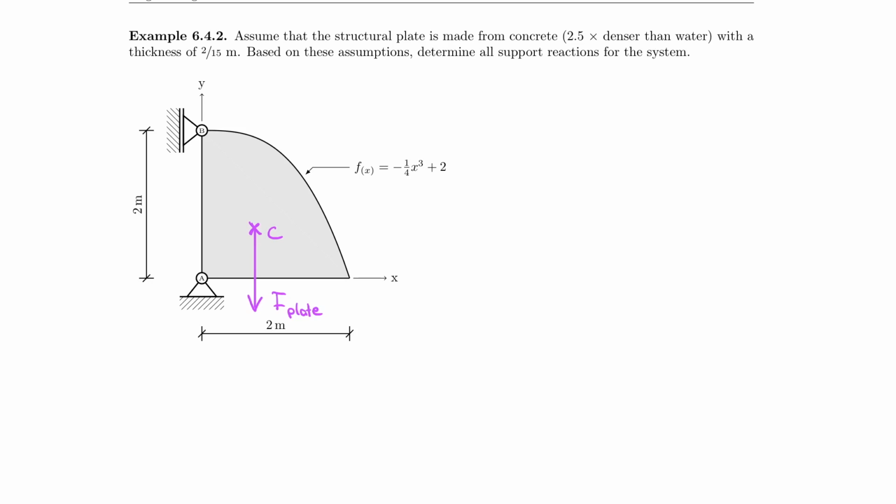And that plate has a distance x bar. And that is what I need to calculate my support reactions, because my support reactions are twofold. I have these guys. I'm going to call this RAY, RAX, and then also I have RBX. And the easiest one to find is RBX.